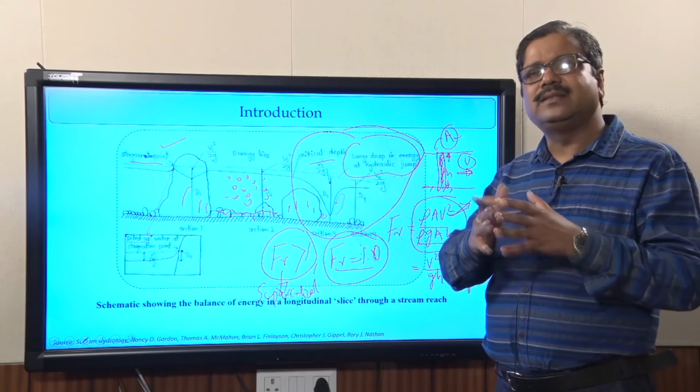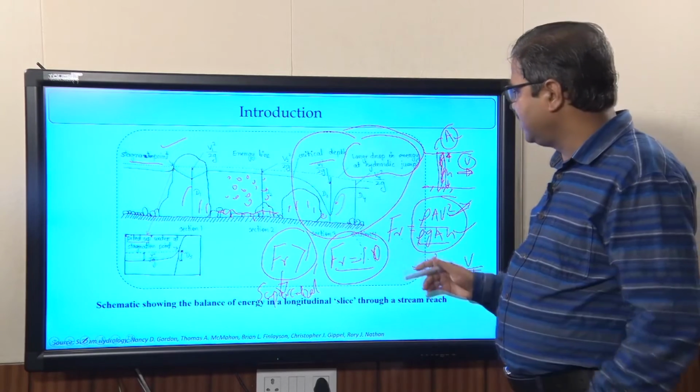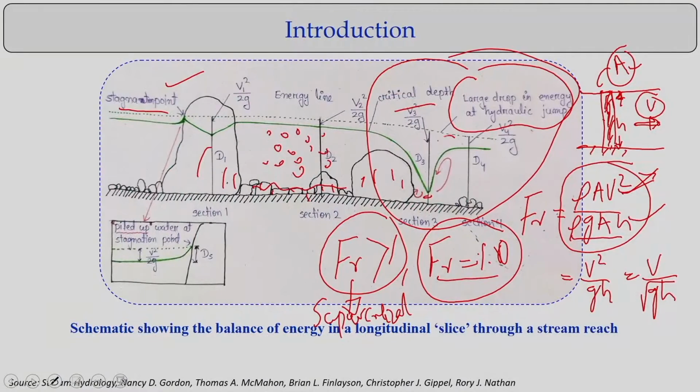During the transition from supercritical to subcritical flow, you will have hydraulic jump formations. Those are the regions where you have a high dissipation of energy. So we use hydraulic jumps as a design for energy dissipation, or for creating turbulent structures for mixing of any fluid, or of fluid and sediment.